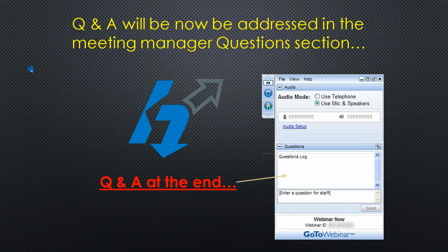Okay. And I think the final question I see here: you were logging the results of your analysis in Excel manually, but does Nastran have a native way to track and reiterate the results within the FEA environment? Not that I have found. I know that's been asked for, but I've not seen it incorporated yet. It's been a couple of releases since I looked for it, but as far as I know, there's nothing there to automatically log those results and chart them.